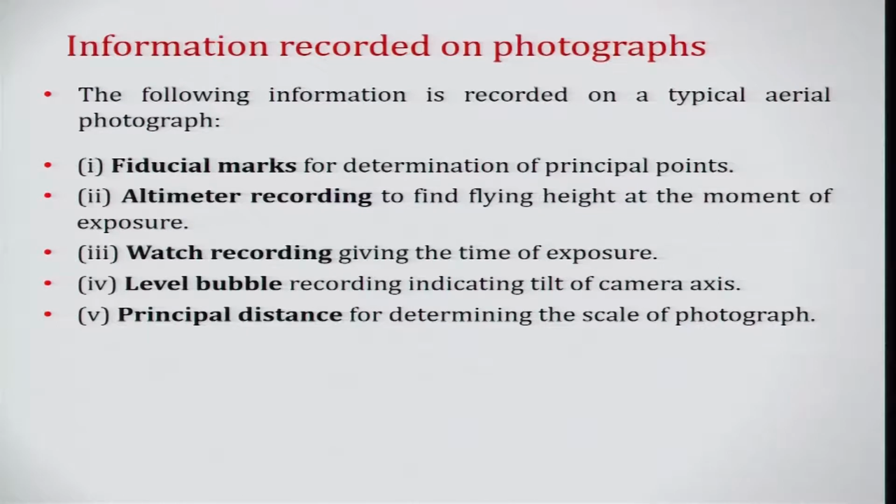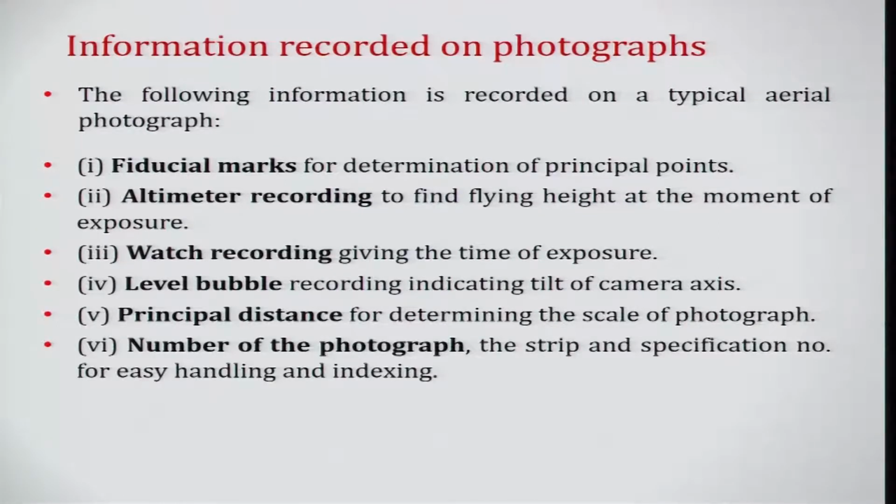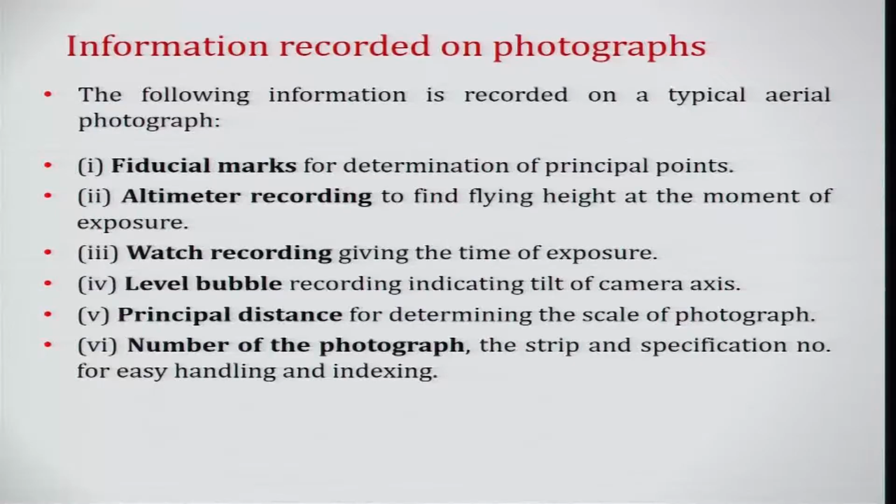or on the map. The number of the photographs is important, because this indexing will help us in putting all the photographs in a catalog, and you can also identify the line of flight. That also helps in picking up the photographs, whether a photograph was taken in a particular line of flight, forward, after, like that. Otherwise, you may have a negative image. So, that is also important.